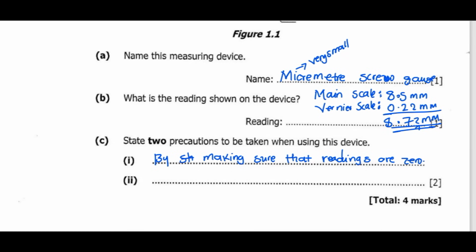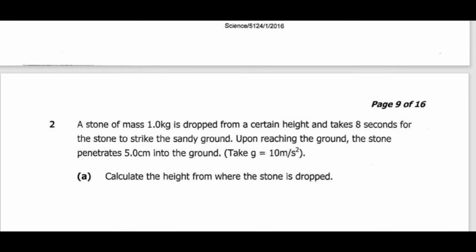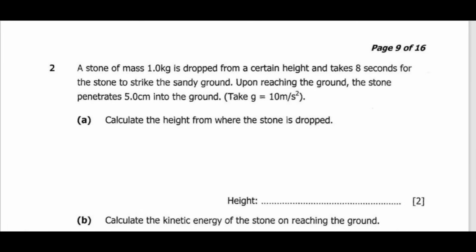Then for the second one, we can say by thorough cleaning. So before you place whatever you are trying to measure, make sure you clean it, because a micrometer is very sensitive. It can even measure a dust particle.